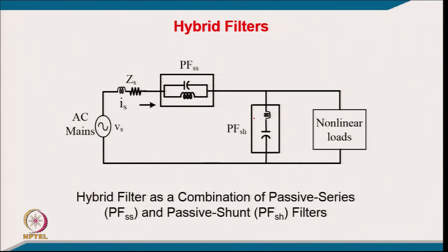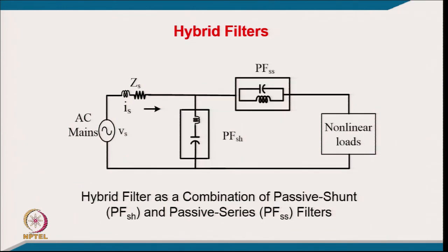Why can it be current fed? Because now you are not going to disturb your load, and the passive shunt filter meets the reactive power requirement of the load, and the load current can still be maintained in the same manner. It is not going to affect your supply system, because you are providing the shunt path for all those harmonics which the load is drawing. Some harmonics you can block and some you can circulate, so it gives a very interesting combination. To some extent you can compensate the limitations of one by another, as I have discussed.